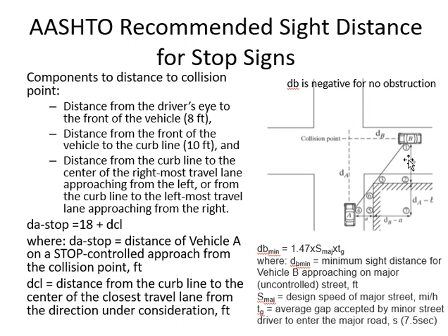Yeah, so the gap is the time interval between the 2 cars on the major highway, so that the minor guy will try to enter. Again a safe value is given, but you can do your own study. We called it critical gap earlier. So according to their study, the critical gap is 7.5 seconds.